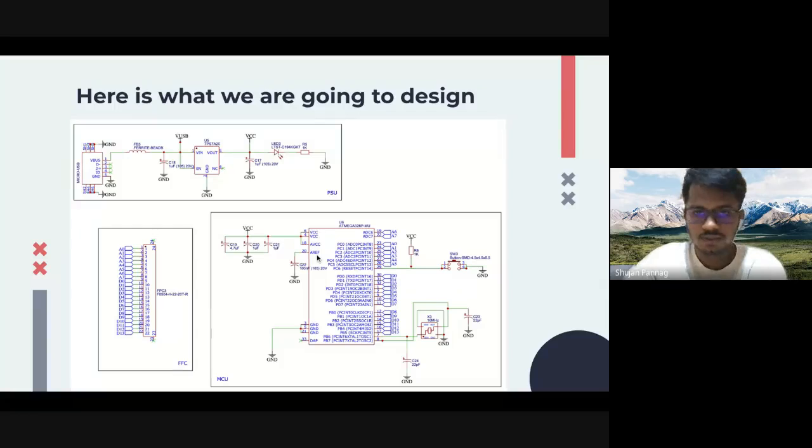And then this is your AREF. This is the reference voltage for your ADC internally. So I've just put a 100 nanofarad decoupling capacitor and shorted it to ground. Again, these are all local decoupling capacitors to reduce noise at every point of your PCB. This is really, really important. When you are doing this circuit, you need to find out where these noise components could really affect your PCB, and you need to involve filtering circuits and compensating circuits right at those positions.